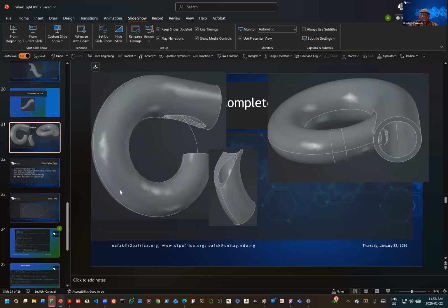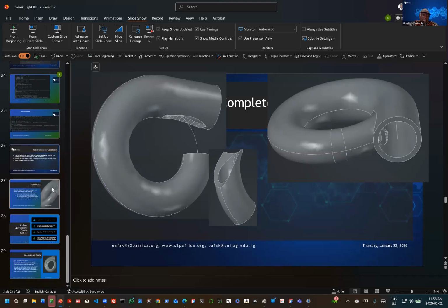If you can't, don't worry, but you should be able to cut the inner portion. What we mean is that the internal portion must be cut open in a uniform way. What you do is let a cylinder interact with it, cut through it, and then do a Boolean operation to remove the part that has been interacted with.